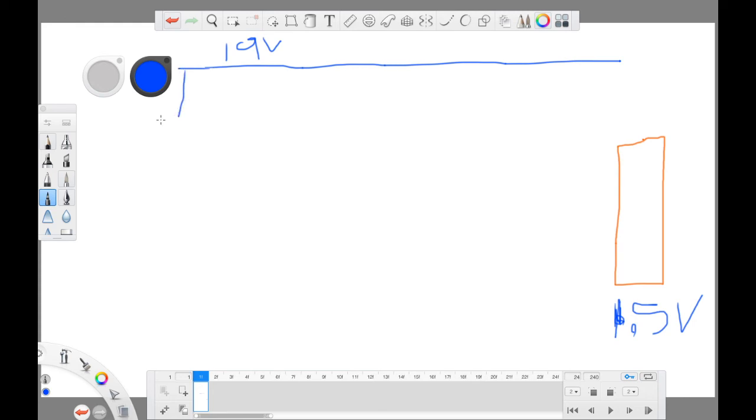I have my tap here. This is my tap. This is my first MOSFET. I'm connecting, and this is my second MOSFET. All connected together. And the second MOSFET is connected to ground, so that the whole thing will be able to turn off. This is why we have the second MOSFET.